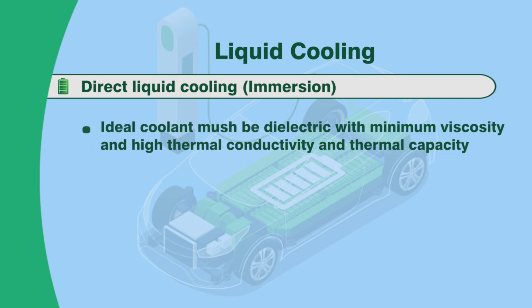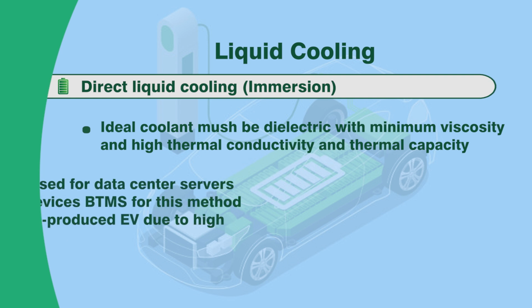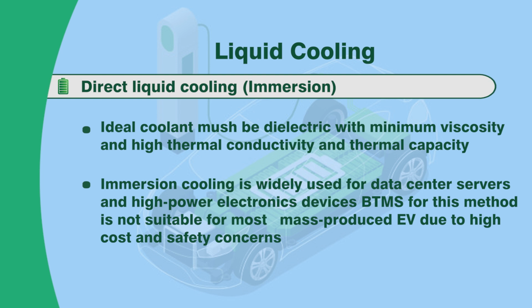The ideal coolant must be dielectric with minimum viscosity and high thermal conductivity and thermal capacity. Immersion cooling is widely used for data center servers and high power electronics devices. The BTMS for this method is not suitable for most mass produced EVs due to high cost and safety concerns. So, this is not a suitable option for electric vehicles because of high cost and safety concerns.